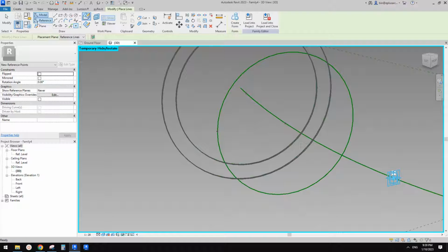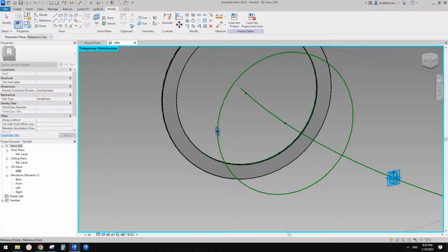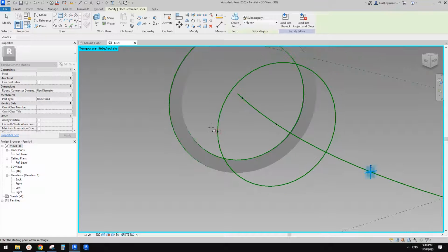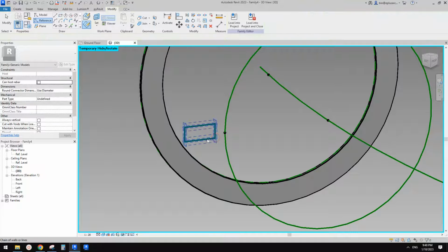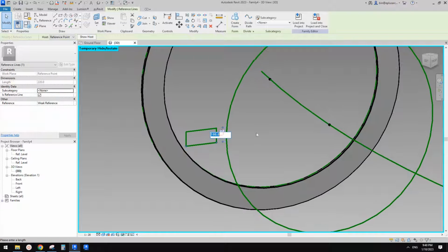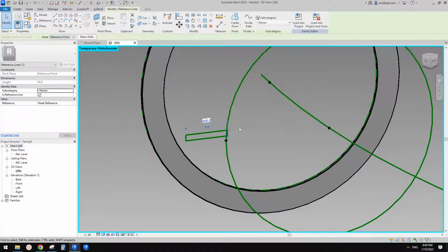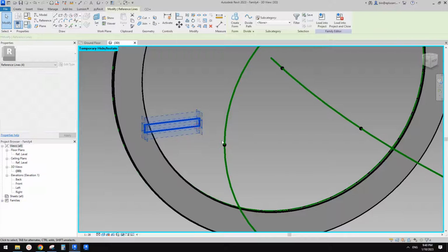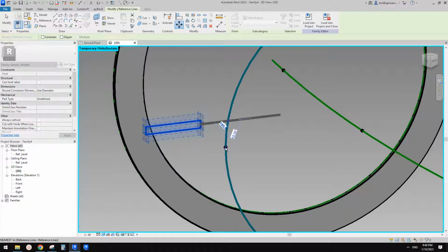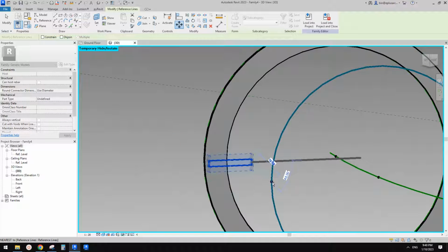And then we can use reference rectangle, draw on work plane, set work plane, and tab, pick this work plane, so vertical, and do a shape. Tab, select, make it like 40, select this one, make it 300, and select the whole thing, MV up and MV midpoint, and try to place onto.